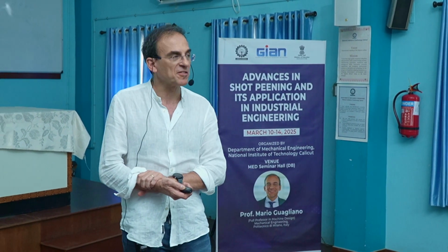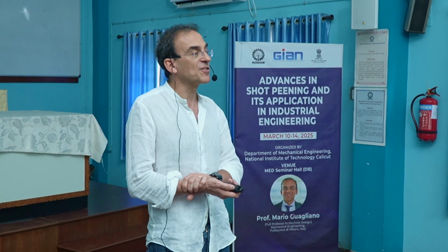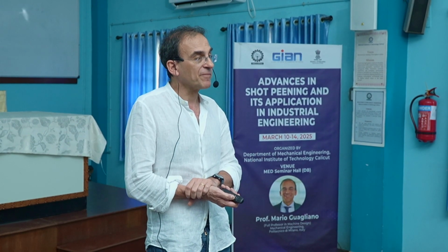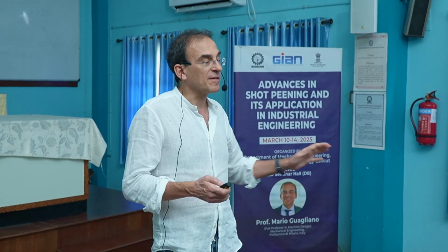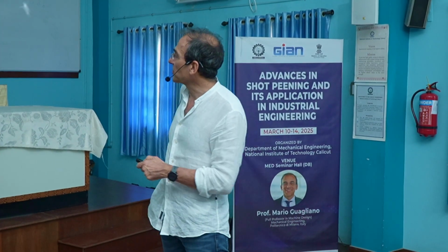Okay, so the number that we read when we perform an XRD measurement of residual stress is the macro residual stress. A secondary result that is related to what I call FWHM, that we will define in a few minutes, is related to type 2 residual stress, that is the microplastic strain and so on. With usual equipment, nothing can be related to type 3, to the intragranular, one single grain residual stresses.